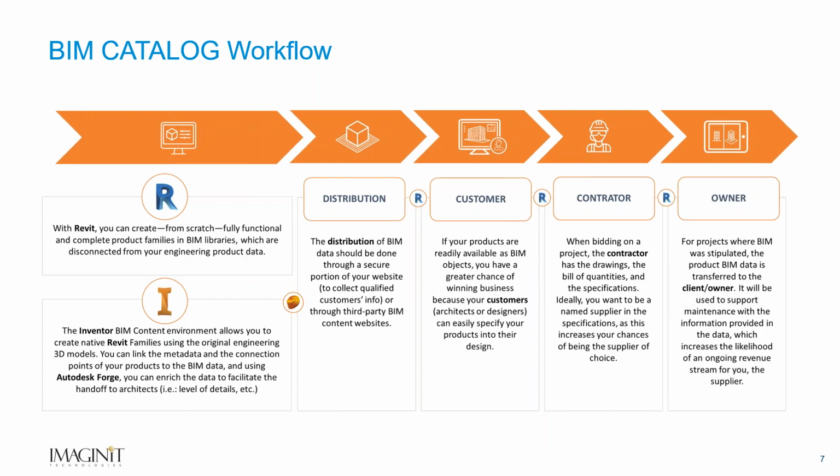It was a series of solar panels that were going onto a building, or maybe it's exterior cladding that's going onto a building that has to be manufactured. I'm creating it in Inventor, and it's standard components. I just want to be able to say, here you go. Here's a standard component. Please use it in all your Revit designs from here on in. So I can take an Inventor file and save it out as a Revit family.